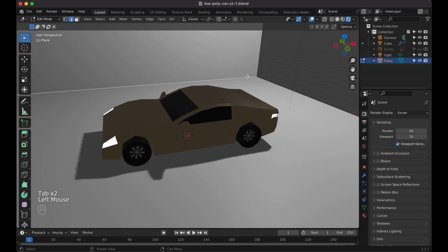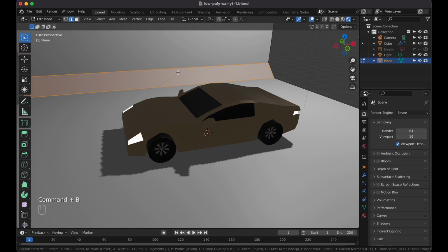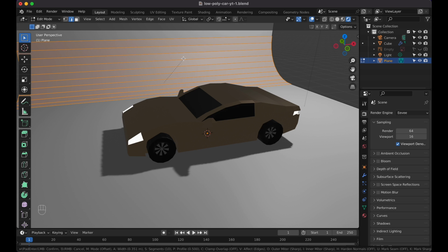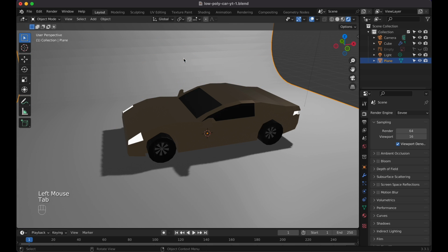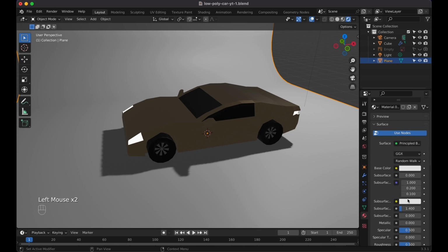And now select this side piece right here, this edge, Command B, Control V to bevel, and basically you just want to make enough bevel to where it's smooth. You can either do it by scrolling up on the laptop pad or your mouse middle button, and then right click, shade smooth. And then what I want to do is add a material to this,